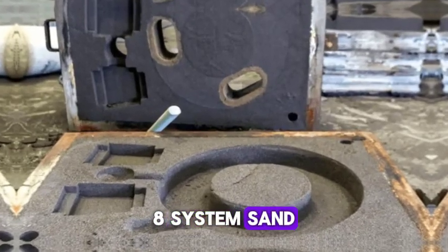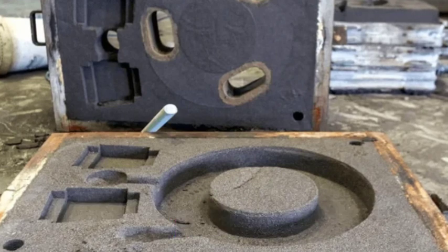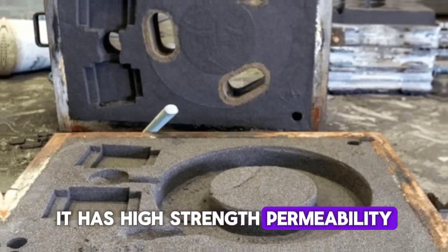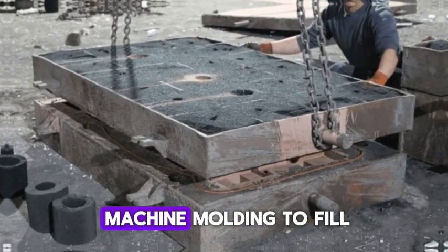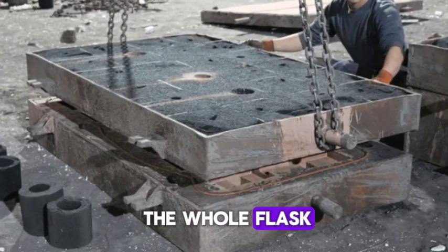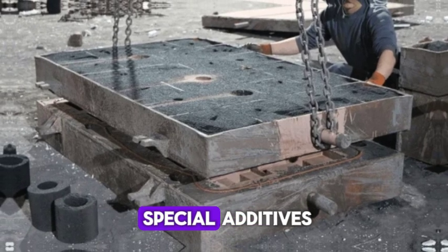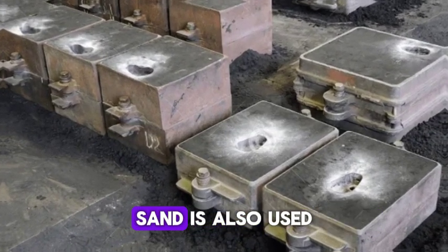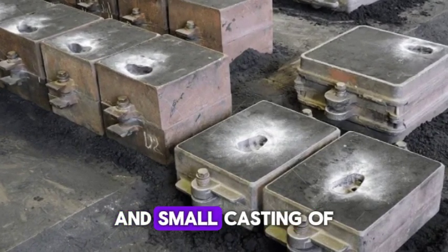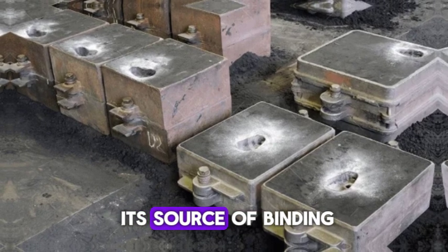8. System sand. This molding sand is applicable to mechanical heavy castings. It has high strength, permeability, and refractoriness. System sand is used for machine molding to fill the whole flask. Facing sand is not used in this molding because the sand is cleaned and has special additives. 9. Molasses sand. This molding sand is also used for core making and small casting of intricate shapes. It contains molasses as its source of binding.